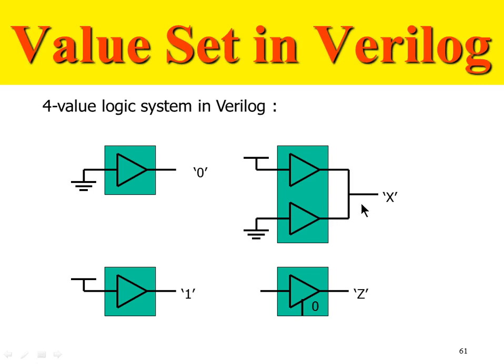In this case, the signal is getting a logic 1 from one side and a logic 0 from the other side, so it doesn't understand what needs to be done and generates X. You should never get X in your simulation. If you are getting an X, something is wrong and you should fix the problem there. Otherwise, synthesis will not work because of this issue.